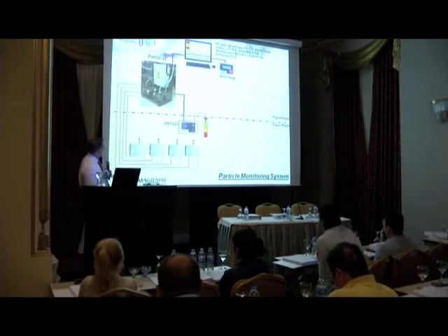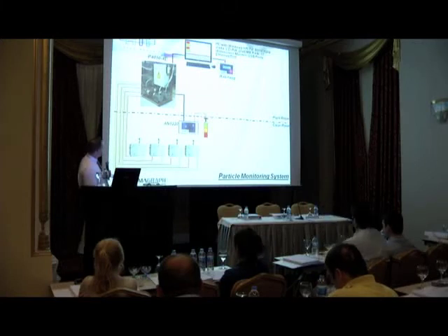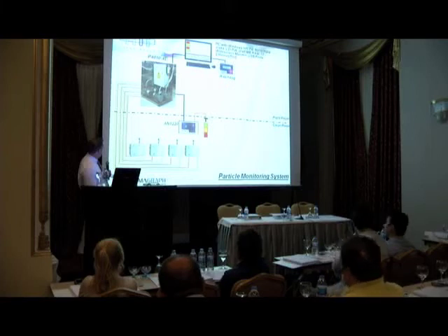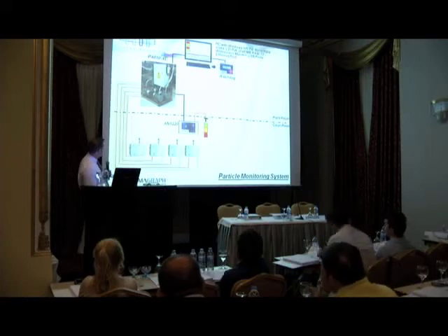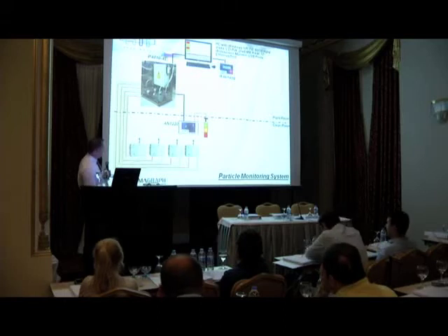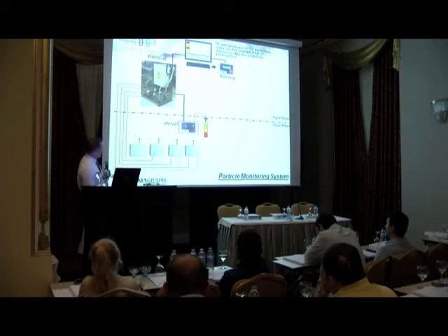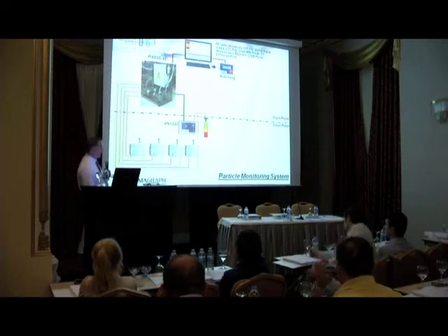The direct interface for particle counting to the PC is a vacuum control panel. In this instance, we've got 4 individual pumps, a vacuum controller, and these vacuum pumps and controllers then link down to these particle counters. Also, you'll notice that we've got connected here an alarm indicator panel. Should we get an alarm, we will enunciate it on these beacons. These devices are configurable either to measure the whole system or specific areas.